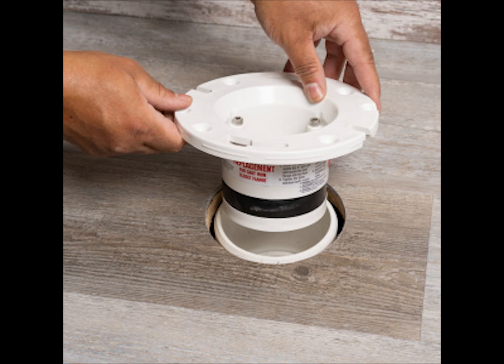Toilet flange on concrete floor, new construction. We use a closet flange. Find the right diameter, don't cut the pipe off flush with the floor. Cut pipe flush with the finished floor, i.e. flush with the top of the tile.